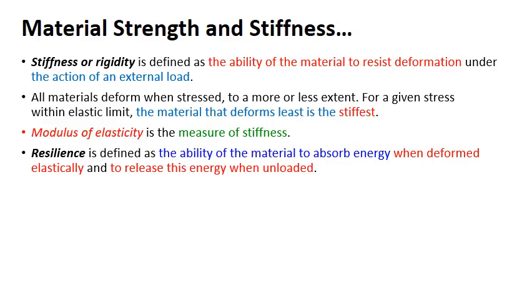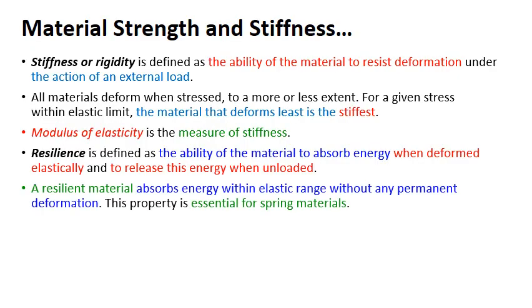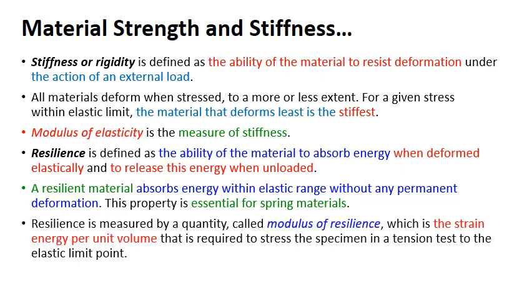It is the ability of the material to absorb energy when deformed elastically, right? And it will release its energy when unloaded. So a resilient material will absorb more energy within the elastic region. So higher the resilience, higher the energy that it can absorb the shock. For example, in case of springs, it is measured by a quantity called modulus of resilience, which is the strain energy per unit volume.